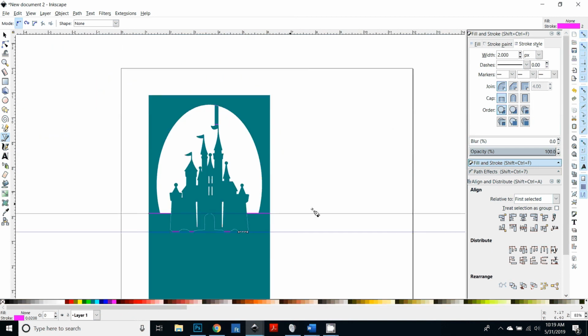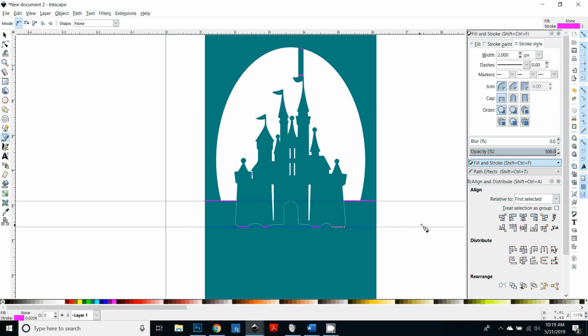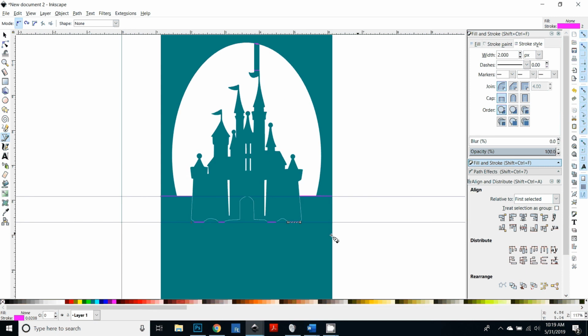Now what I want to do is select all of those purple lines that I've just made, and make them one thing so that I don't have to worry about them getting unaligned. Now you know when you're making objects one thing, you do path union. If you've just got strokes that you want to make one object, you will use combine, and that is one difference between combine and union.